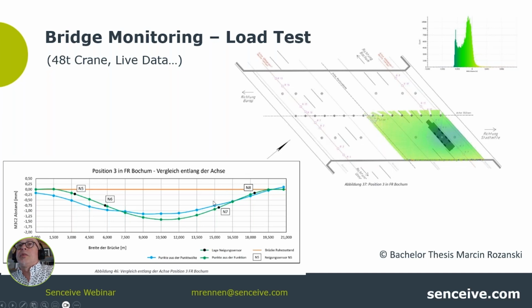And so the suggestion would, of course, be to define some alarm thresholds, so that an alarm would be triggered when eventually this trigger value is exceeded, and that would then cause the surveyors to go there, do this scan, and compare it with the reference scan. Then nobody has to be permanently or regularly going there, but the automatic system would fulfill this observation task.